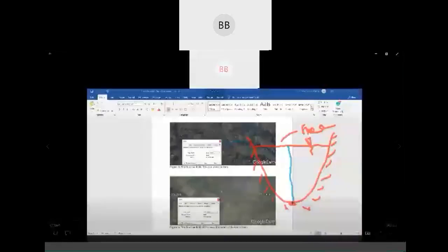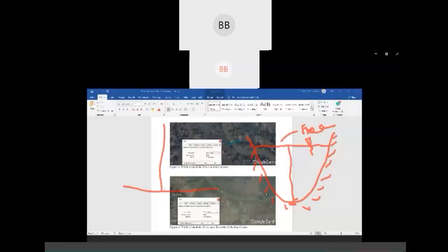As you can see here at the bottom level, your friction is more with the bottom of the channel. So for the bottom of the channel, we consider the velocity to be zero. And from zero, when we move upward, it increases.